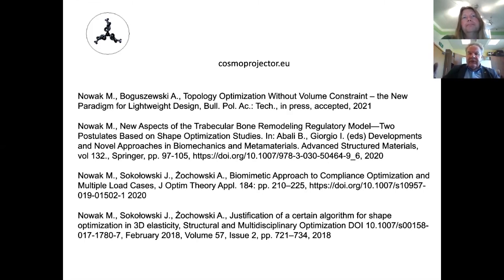So when I find the information that in this area I should add some material, I add it, but not by means of finite element methods, like adding other elements or changing the parameters of these elements. I just change the geometry and then go back to the mesh generation and produce a completely new mesh. In this approach it is also important that you can easily produce holes, or put some areas together. There is no problem.